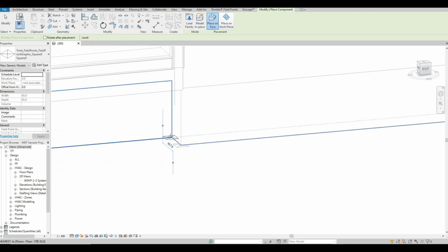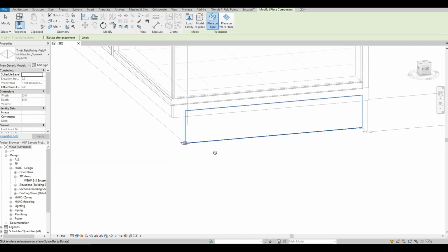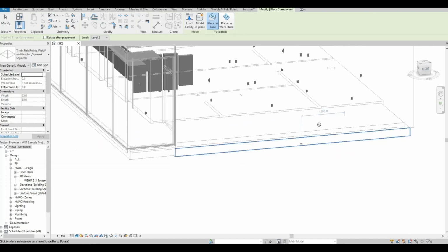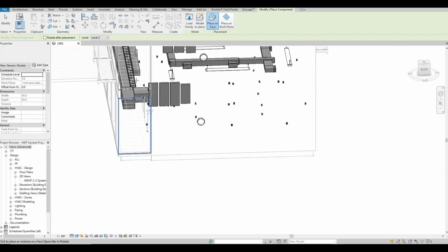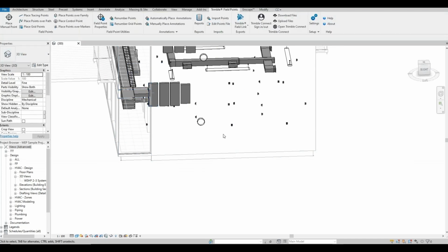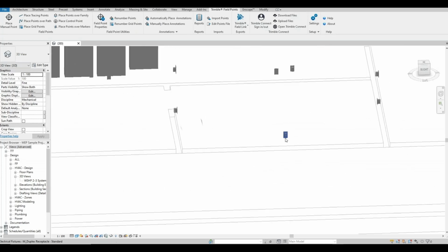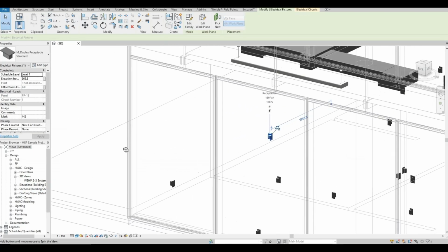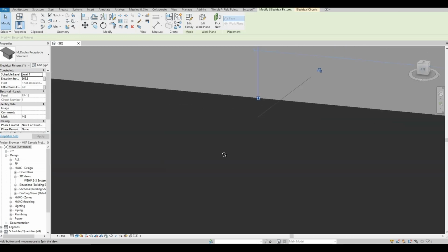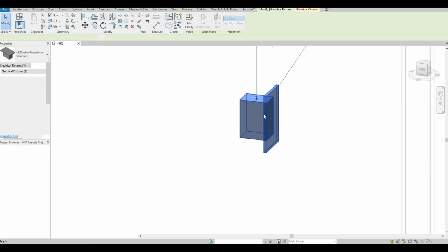If I choose over here as well, let's say I just wanted to set out some of my structural slab corners, I can generate those points there. So those points now, if I just wanted to generate points manually, I could click as many times as I wished across the site and generate those points for setting out. But what we're going to do is generate some automatically here. If I select here, we have some form of receptacle. I'm going to say across all of these receptacles here, I want you to generate 4 corners across this family.